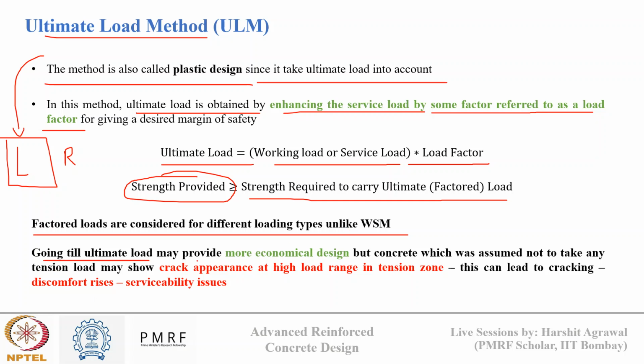Going up to ultimate load will provide us a more economical design, but concrete, which was assumed to take no tensile load, may show cracks at a higher load range. Since we are going to such a high load level, multiplying some loading factor on the load and then designing, there can be cracking issues in the concrete, and thus there can be some serviceability issues in the design.